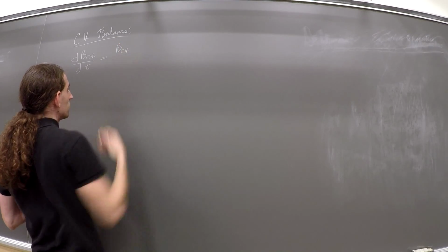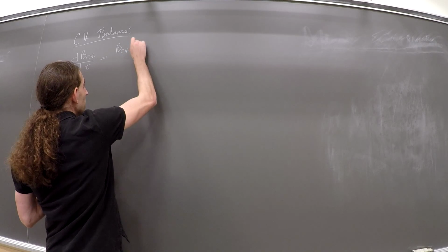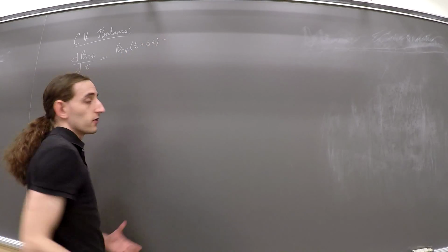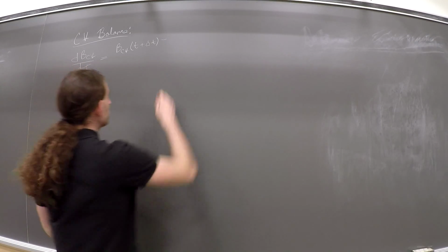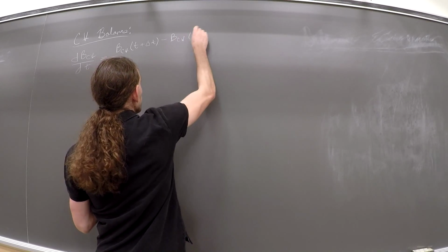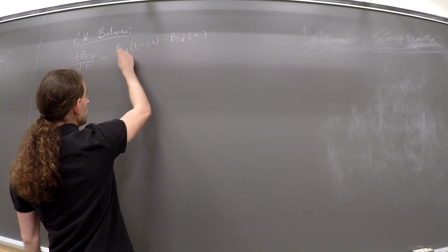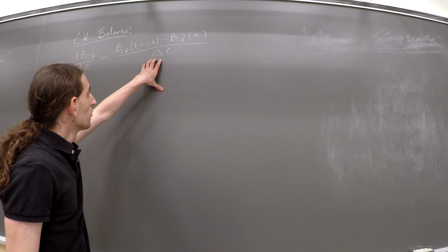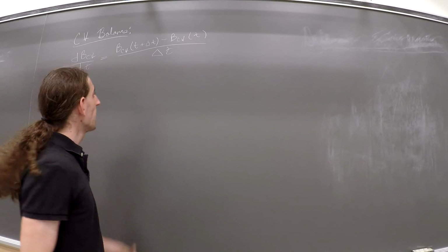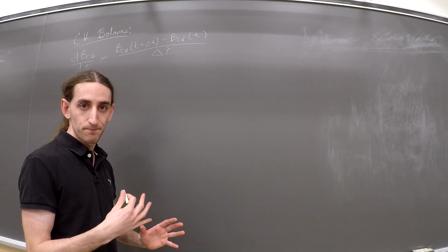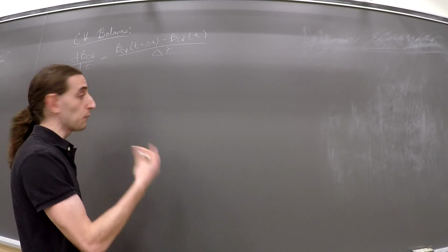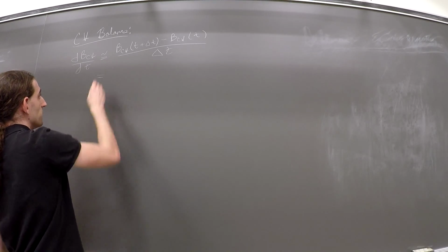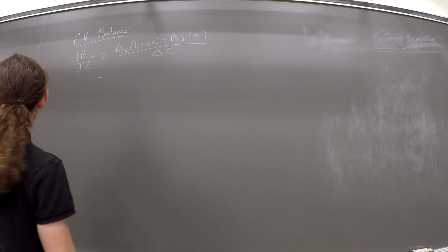We can take some time delta t, and we can take the definition we just had of B of the control volume at time t plus delta t. That's our final state we're analyzing. And we can subtract away the initial portion of our extensive property B, and then divide by delta t. So this is an approximation, okay? So we could take the nice terms we just derived, plug them in here, rearrange things, and take a look at what we get. Again, this is an approximation, so I'm going to put an approximate sign right in there. So let's do what I just said. Let's take the properties we just derived, put them in, and see what happens.